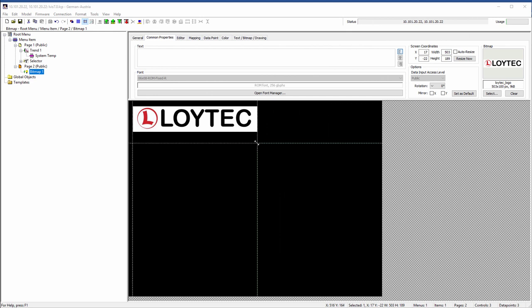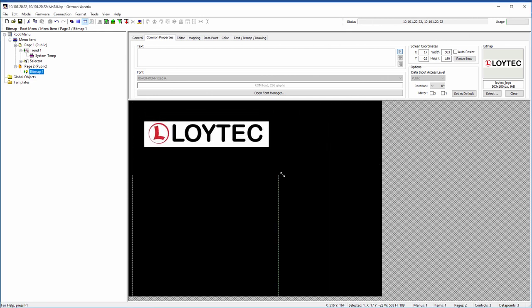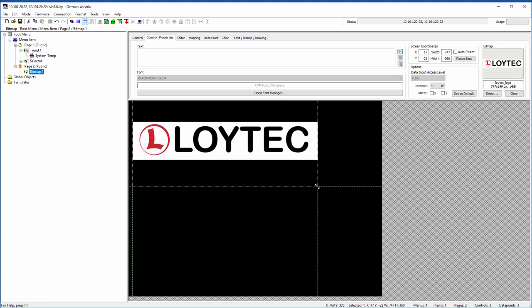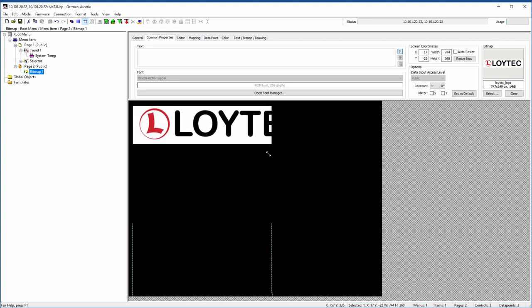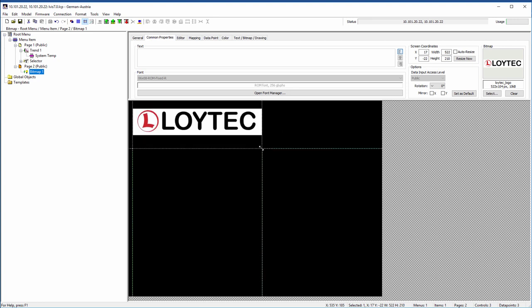Bitmap controls can be resized even after images were assigned. Any assigned content will automatically be scaled to fit the new control size. Instead of adding copies of the same image in different sizes to the image manager and picking the desired image size for the control, only one size of each image is required.